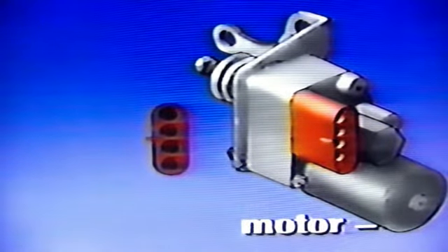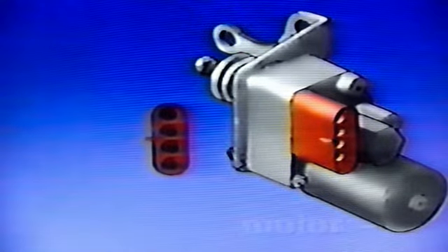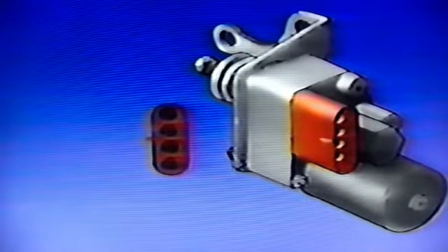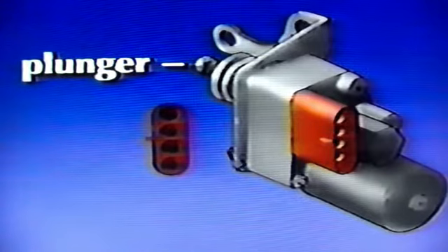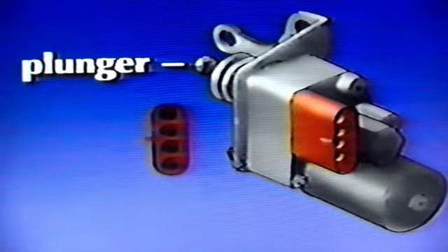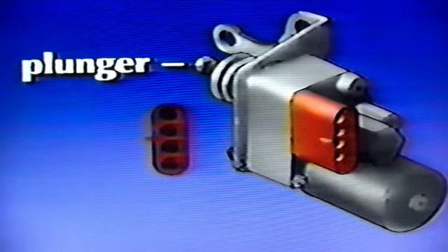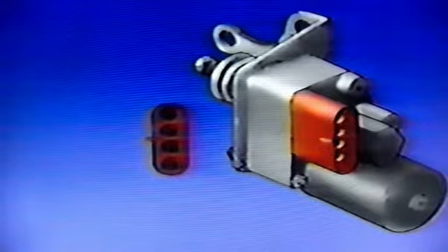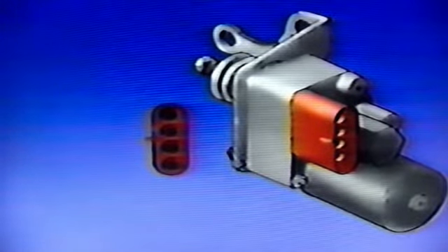Another output control that's mounted right on the carburetor is the idle speed control motor, or ISC. Like a power door lock motor, the ISC uses a reversible current motor. Energize the ISC with one polarity and the plunger will extend. Reverse polarity and the plunger will retract. When a car is equipped with an ISC motor, the computer is in control and there are hardly any idle speed adjustments you can make.